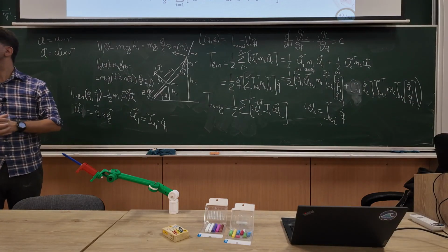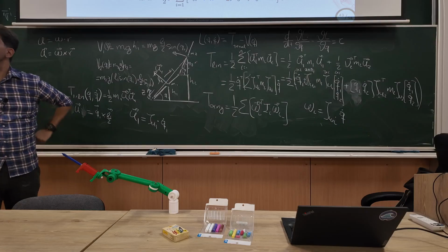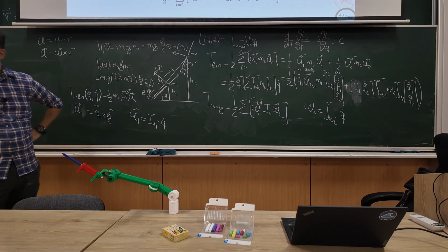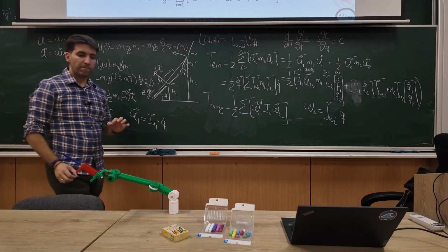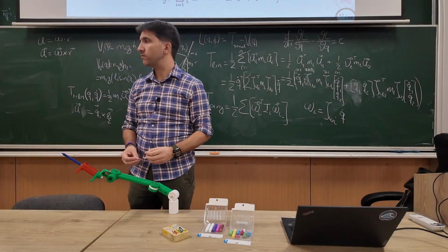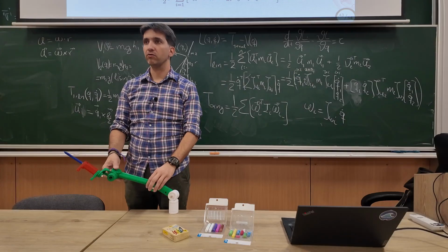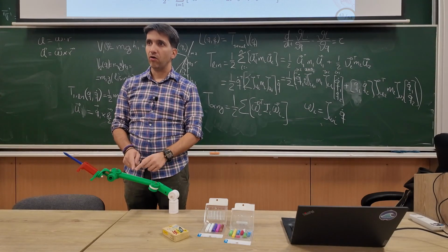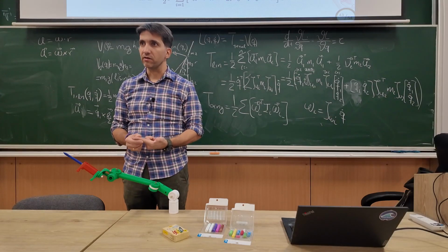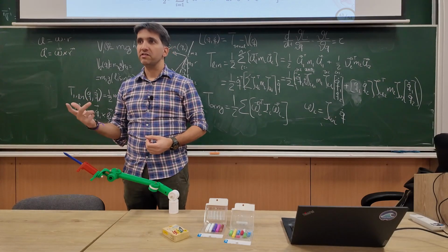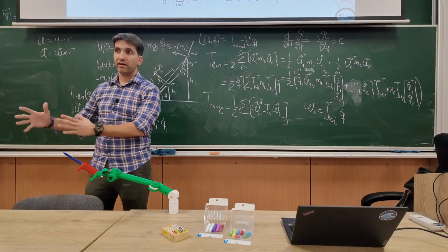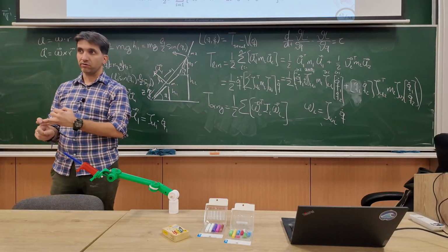I have a question. Could you repeat, please, why we use the Jacobian to go from the joint angle to the kinetic energy? So we want to calculate the kinetic energy of the system, right? That basically boils down to calculating the velocities of the masses of the system, linear and angular velocity, right? That's what the Jacobian does. The other thing is that we want the Lagrangian as a function of Q and Q dot.